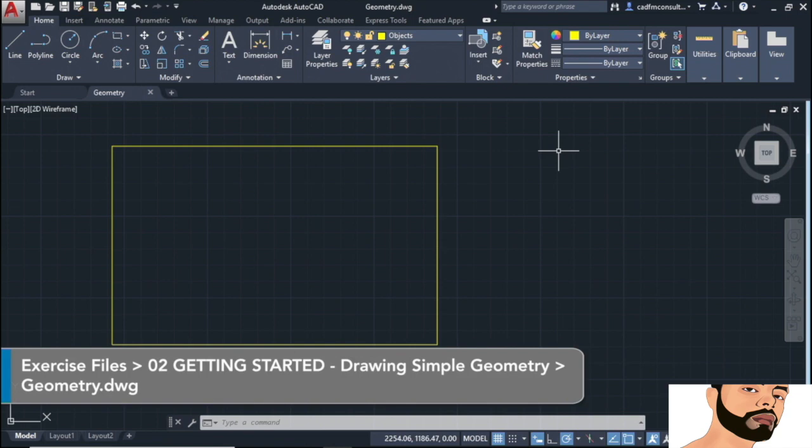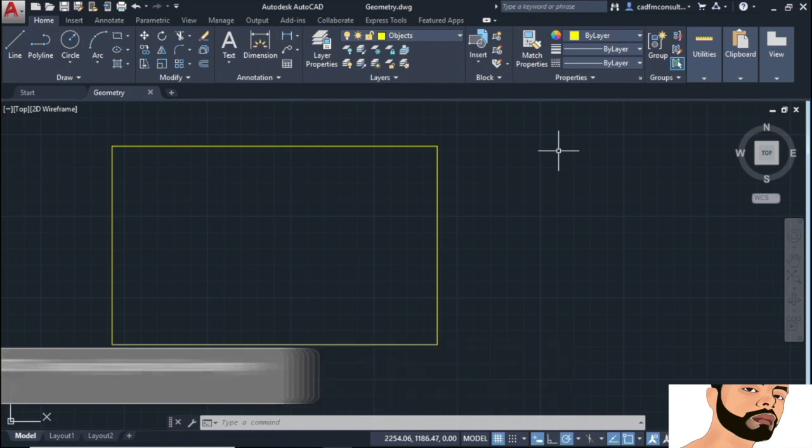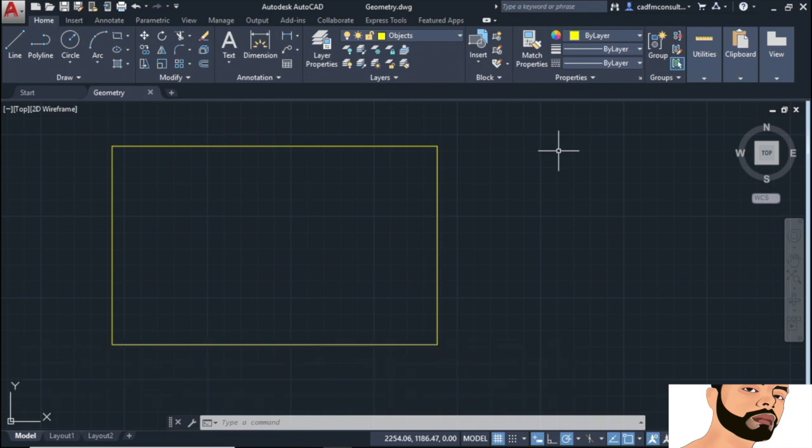geometry.dwg file, and we're going to look at some other drafting settings now, which are polar and also ortho. Now, polar allows you to draw lines to specific angle increments. Ortho ties you to orthogonal angles, which are basically in the X and Y direction. So up and down and left and right. Let's have a look at polar tracking first and see how that works.